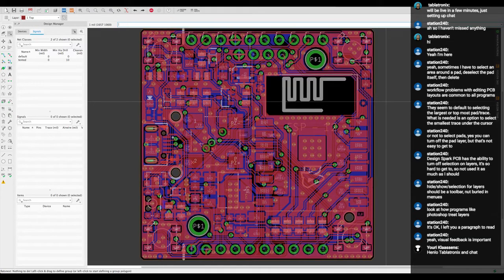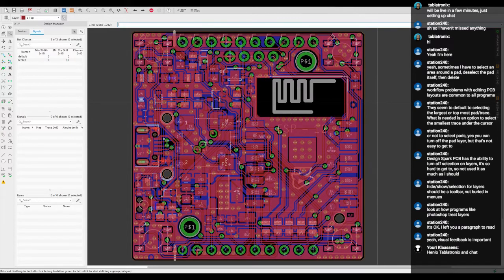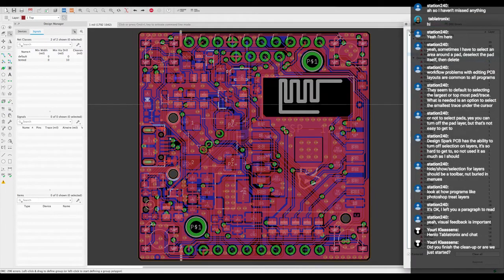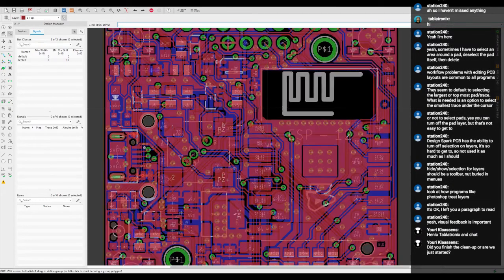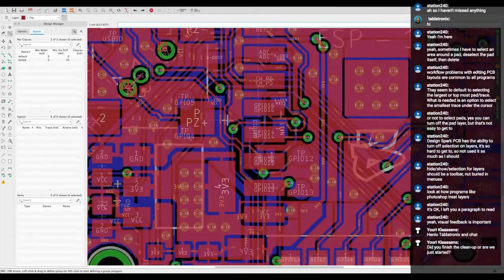I'm more interested in putting this into projects as a project kit and then making different projects from it and maybe selling those projects. Pretty much finished. I was doing the DRC and cleaning up some of the angles. There's like an angle DRC you can do. Some of the traces were just weird angles and I cleaned them up. And now I'm just going over what was changed.